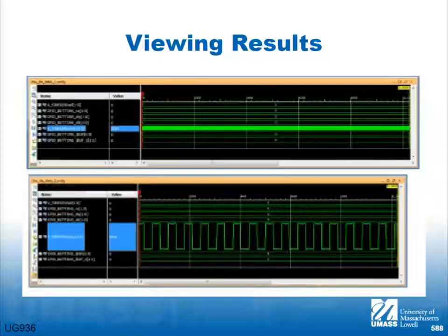If your simulation requires external components, that might be hard unless you can get that information from some other component into the FPGA. But what this is first of all, something that allows you to correlate actual behavior to expected behavior by running the simulation and then running the logic analyzer on the part and comparing them. And you can dump files out of both the simulator and this and just do a post-processing on it. Done it 1,000 times. I don't know about 1,000, but I've done it a lot. This is an extremely powerful verification tool, finally, right? We talked a lot about debug, but don't hesitate to use this method for verification.